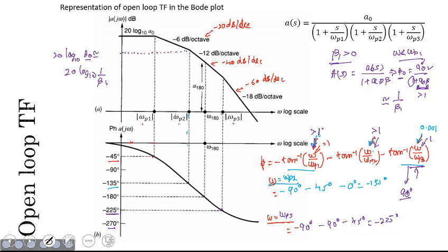And this is the closed loop transfer function, and the moment I reach here, what would happen when we try to intersect at this particular junction, right? Will the gain stay as it is, or will it tend to bend and have some degradation in our result? What could happen? Let us pause for some time. Now it's obvious that this A naught at this particular frequency, somewhere closer to omega p2, is not the same as we had it over here, right?